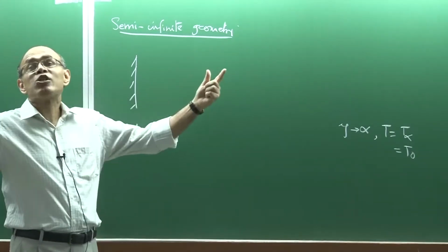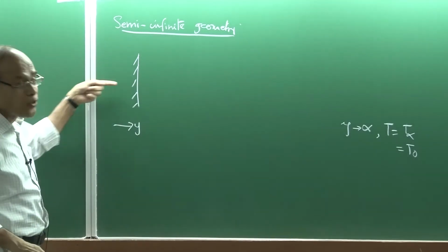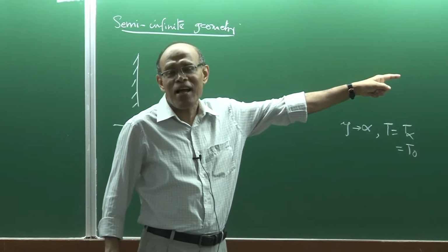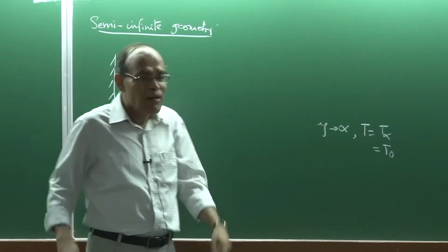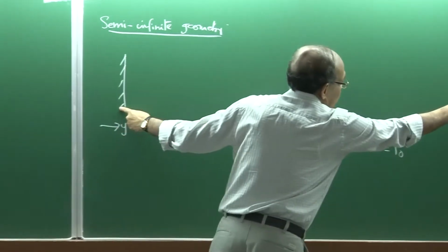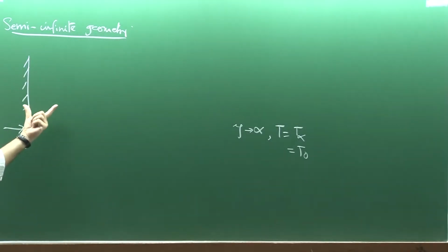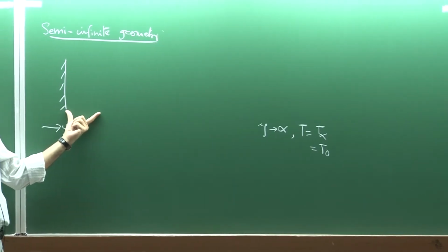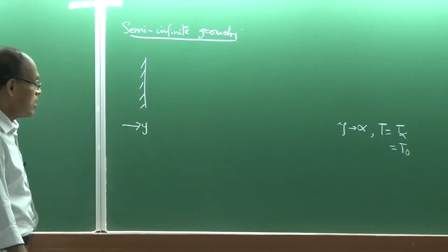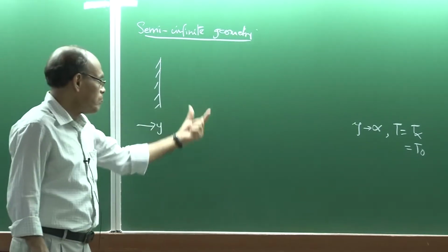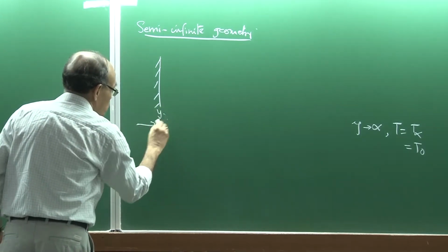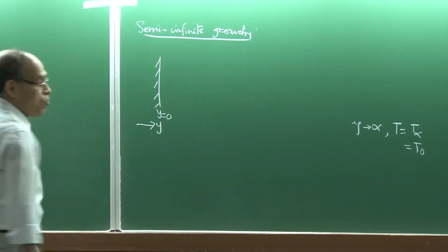The domain actually is so thick that the heat which is penetrating through this surface really does not see that there is another wall, and it takes infinitely long time, which for all practical purposes is not significant for us. So, we do not have to go this far, the heat is within the time zone of interest, because it is an unsteady state heat conduction. Therefore, the penetration of it is going to be restricted close to y is equal to 0, which is one of the boundaries.